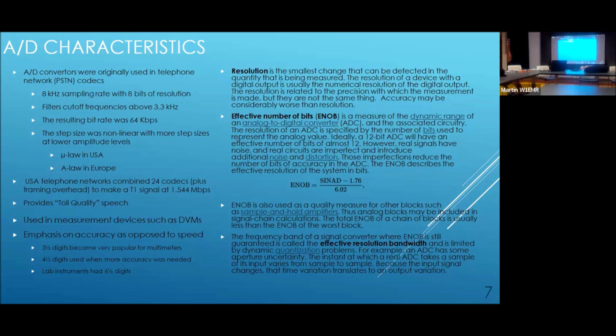So if you have an 8-bit thing, theoretically, you could get 48 dB out of it. Now, if you have a 16-bit A to D converter, 6 dB times 16 is going to give you 96 dB of effective resolution. And now at 16 bits, you're approaching some pretty hard limits. All right. But the industry has been making 24 and 32-bit A to Ds.